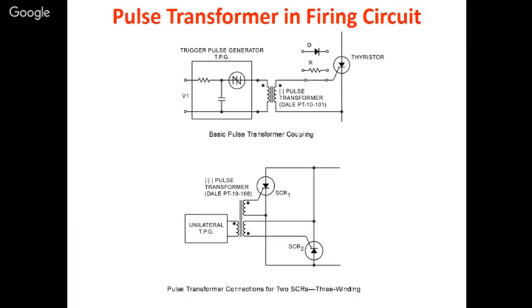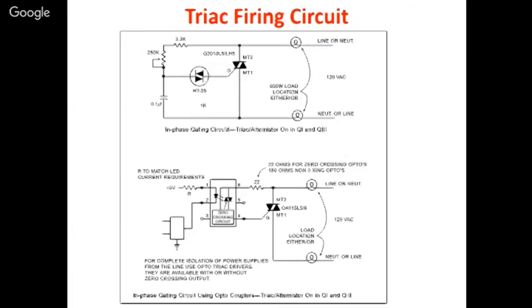Or some 12 volts. Sometimes the thyristor may require 24 volts, or sometimes even 9 volts or 12 volts. In that case, you have to drive that voltage. For that, you use driver ICs. Okay, so the pulse transformer is just used for isolation purposes.